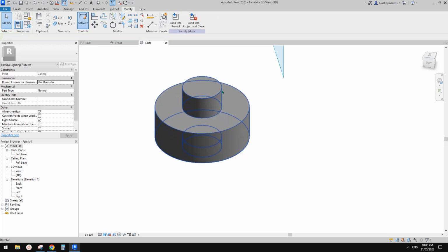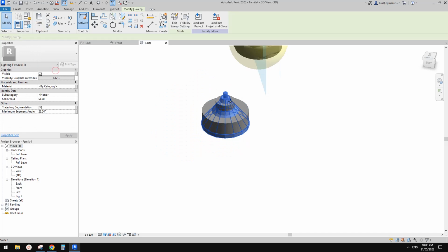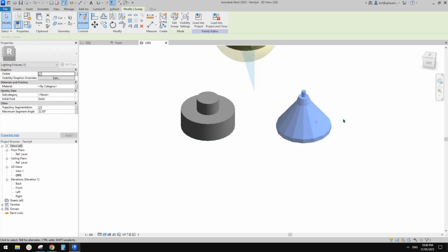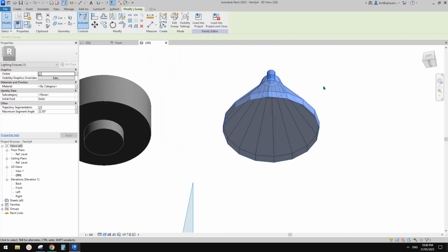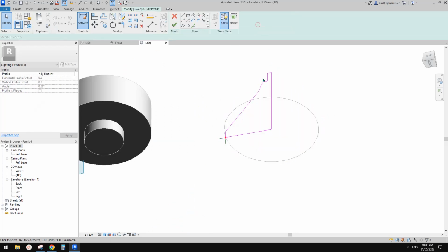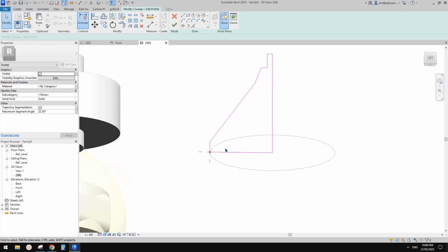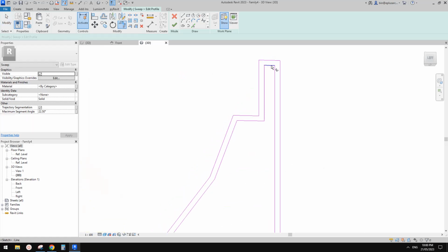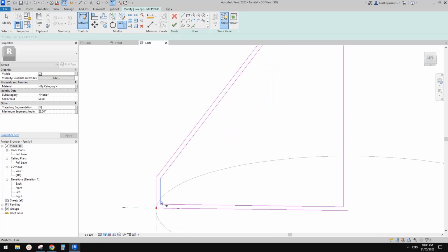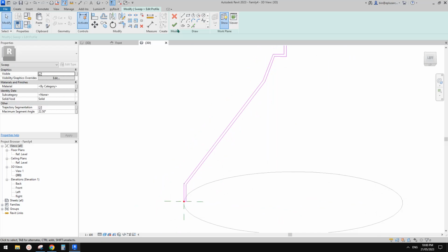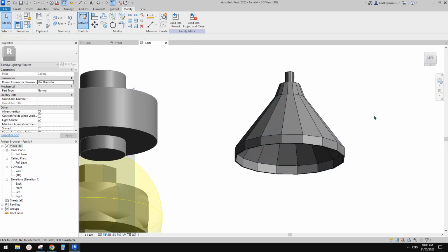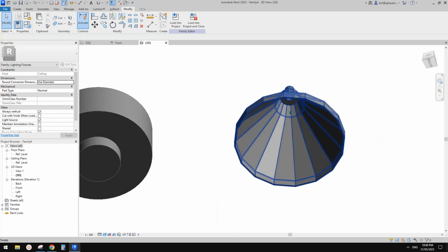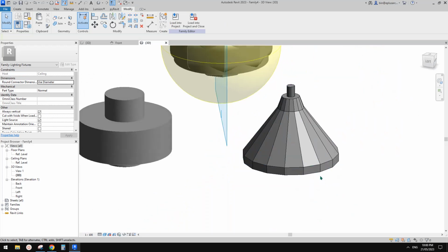If you Control X and paste in same place, you can move it away from this. Okay, so that's how we can do it. And you probably don't want it to be solid, so if I offset this whole thing by 5 mil and trim it here, it becomes something like this, and then you can just add a globe inside, and that's the family.